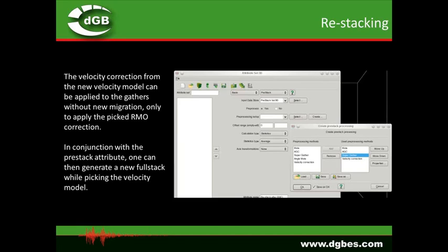So all these steps are run sequentially on the PreStack data store, and the output of the PreStack attribute will be the new full stack seismic data set, or you can even do any angle stack, so between 2 and 32 degrees, if you input angle mutes in addition to these pre-processing methods.